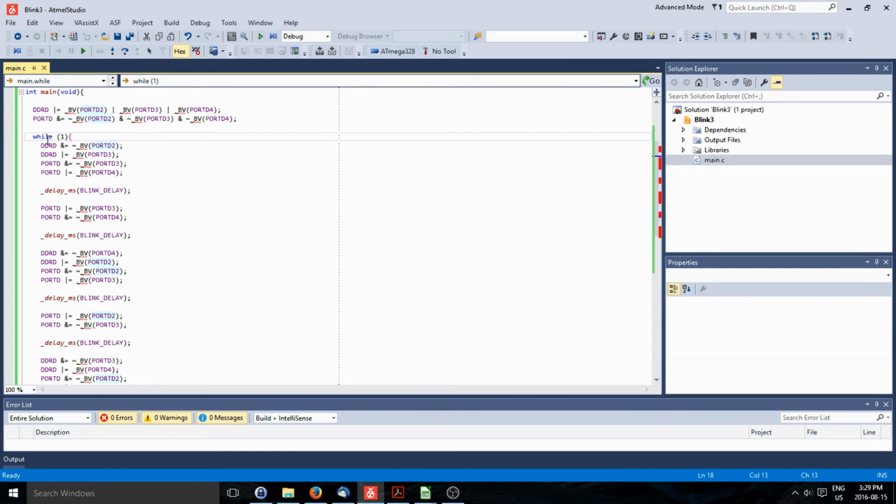So what I'm doing here is I have to set, initially I set all of the data direction pins for the data direction register for those 3 pins. I made them all outputs. But remember when I described how this works, one of them has to be an input, because if it becomes an output, it can affect some of the LEDs that you don't want to be turning on or off. So what I'm doing here is making pin D2 an input. Sorry, pin D2 an output.